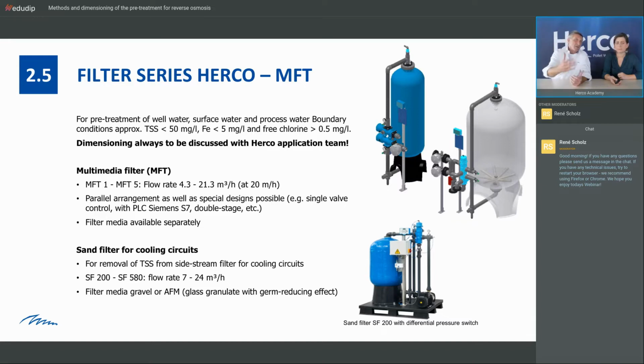But the other thing we have in our product portfolio is a sand filter for cooling circuits. And there it's a completely different aim. We want to have less dirt in the cooling tower system than before. It's only a particle size bleed off system for cooling towers. Oh, okay. And I think that's why it runs with higher filtration velocities. Absolutely, yes. It's not really important if there is a breakthrough. If there is a breakthrough, then it has to be backwashed. And the backwash is normally also partly a bleed off you need anyway for the cooling circuit.